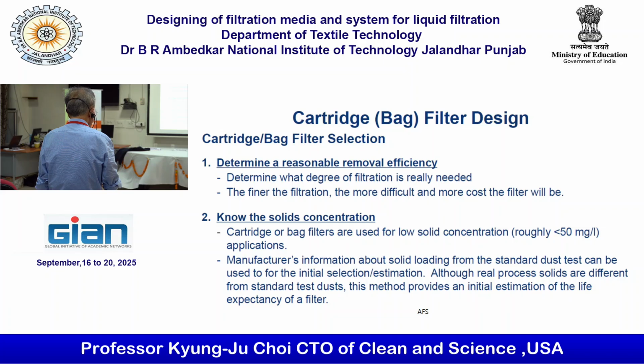Cartridge, bag filter design. First, determine the reasonable removal efficiency and know the solid concentration. The cartridge bag filter is used for low solid concentration, roughly 50 milligrams per liter.